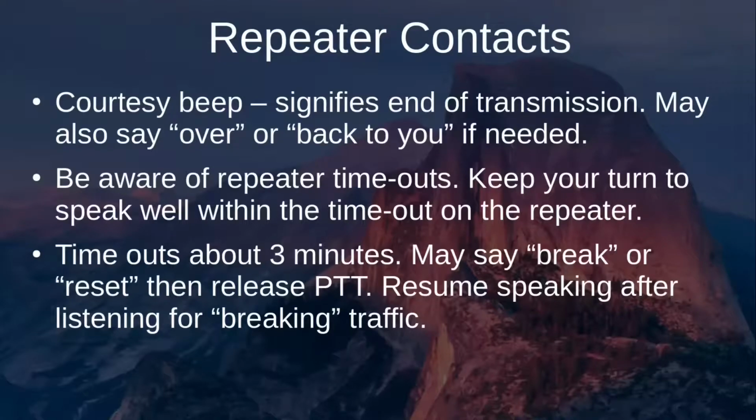So if you're coming up to maybe 2 minutes and 50 seconds and you continue to speak, you can say reset and then release the push to talk button and then listen for any incoming traffic or emergency traffic, and then go back to pushing the push to talk button and continue your conversation. So again, you can utilize the term reset or break and then release the push to talk button to reset the repeater timeout sequence, and then go back to your conversation once you listen for any potential breaking in traffic or emergency traffic.